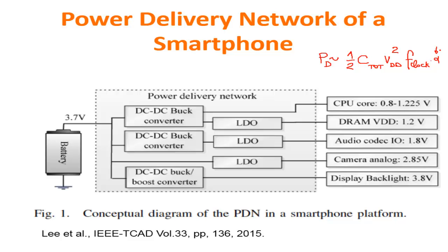In the current use of CPU, what happens is that when the load is low, so you do not need that many computation cycles per second, one wants to decrease the clock frequency. And which is good because one can decrease the power consumption. And actually, if you decrease the clock frequency, you are also able to reduce the power supply voltage.